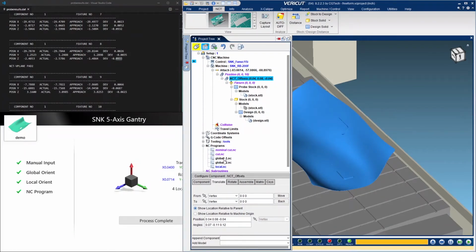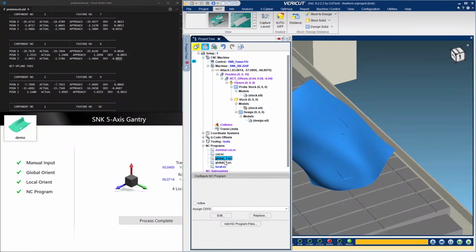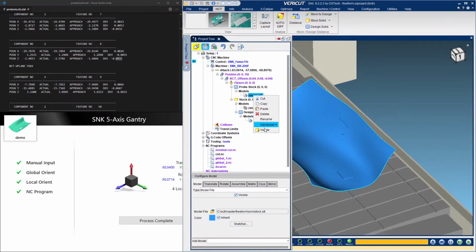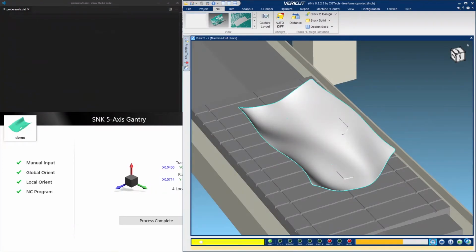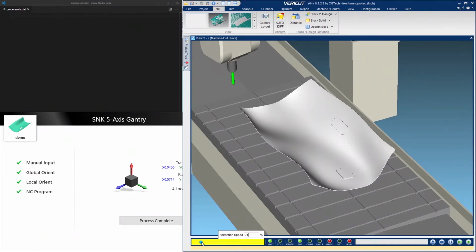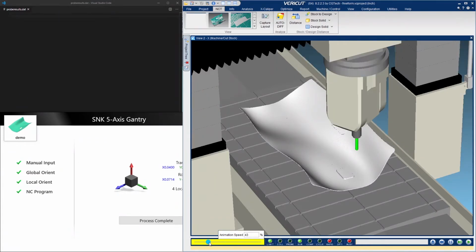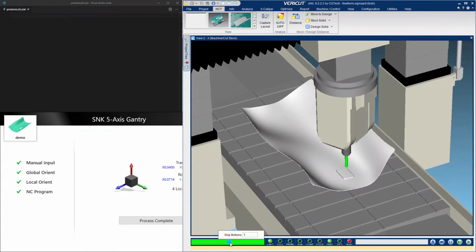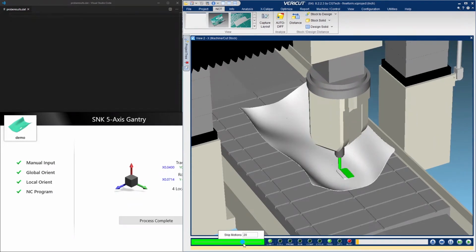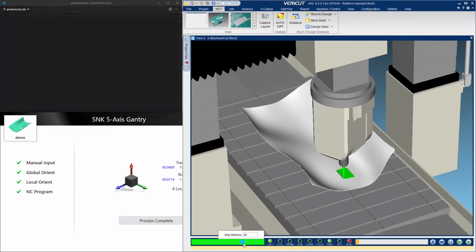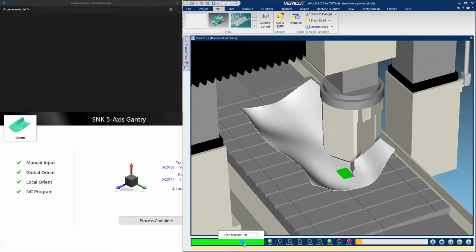Now the only thing left to do is to run our transformed cut program. And to do that, we'll go ahead and turn off this special probing stock. We'll turn our stock model back on. And we'll run that cut program. Then we'll do an auto diff to ensure that everything went smoothly and as planned. We'll speed this up a little bit, color the top surface of those pads. And then when that's done, we'll use our 1/4" ball end mill to blend in that pad surface with the existing contour.